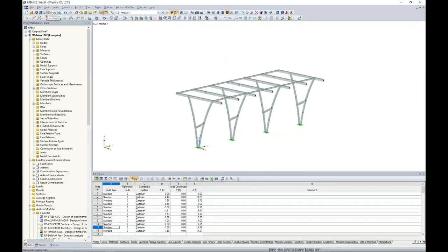Now for impact load, this comes from the ASCE 7-16 and specifically section 4.5.3 for vehicle barrier systems. The code tells us that for impact loads, we should consider a 6 kip load applied anywhere between 1 foot 4 inches to 2 feet 3 inches above the floor. So for this application, I want to consider an impact load on my center columns here.